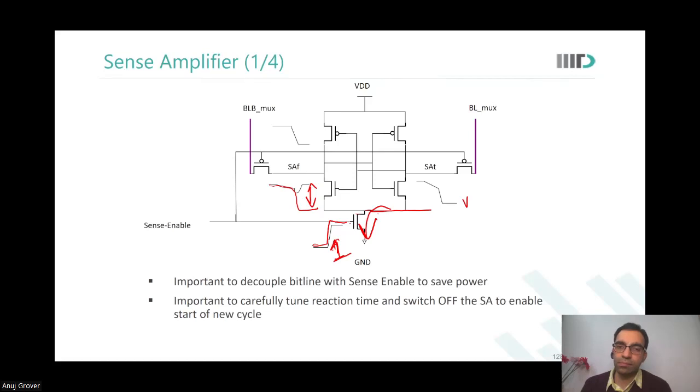So how do we know when to make this sense enable 1? Is it a particular time or something? Yeah, we talked about this. You remember we talked about replica path, reference path? Yes, sir. That is how. Okay, sir. That is also written over here, that you have to carefully tune the reaction time and switch off the sense amplifier to enable start of a new cycle.